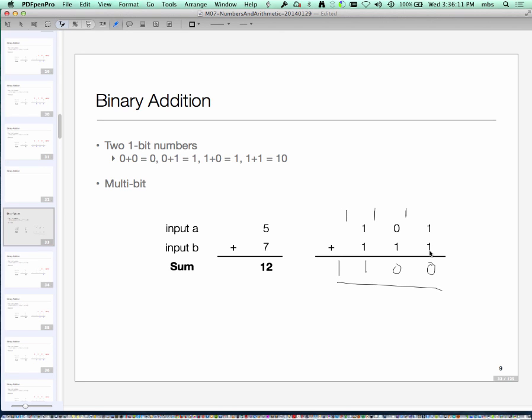Right? So what's happening is at every bit stage, if you think about it, I'm computing two things. I'm computing the value at that bit position, and I'm computing the carry. And in every bit position, I have three inputs: the A and the B bits, as well as the previous carry, just like in regular addition, the 2 digits and the carry.